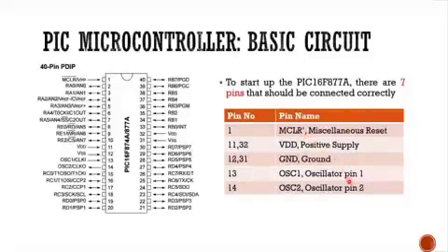Okay, so we start by referring to this figure first. This is PIC 16F74/877A. The code here states that for these two, the setting would be the same. I will refer to this as 877A since you are going to use this throughout this semester. This is the PIC microcontroller, 40-pin dual in-line package, and each pin has its own respective function. Certain pins have more than one function.